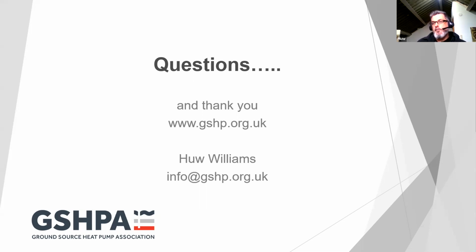And then going on to the operator, answering that for the designer and operator of the system, we obviously want to know whether the system adversely impacts others, because there's a right to claim back derogation issues if your system impacts another. And if there's someone upgradient of you as well, you want to know before you put your borehole in, are you going to be abstracting much warmer water because someone's got a cooling dominant system next door to you? So absolutely, that's all part of what we can model, and what we should be modeling.